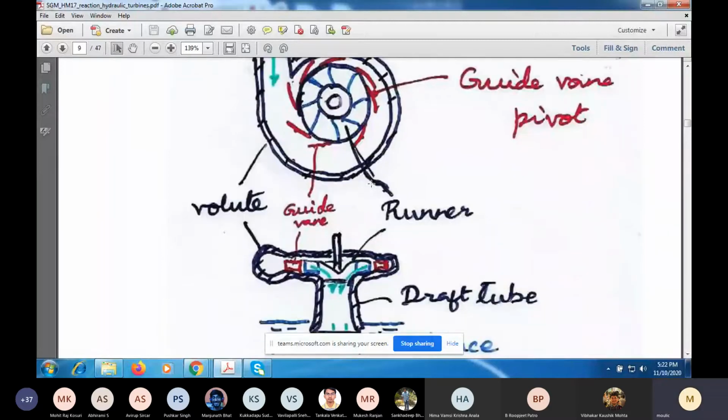Now, I've shown the other view. Okay, so the volute appears in this case, the flow, as you can see, this side and this side are not symmetric because the cross-section area has changed. Okay, and the red lines here indicate the edges of the guide vane.